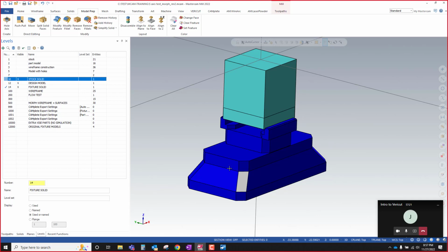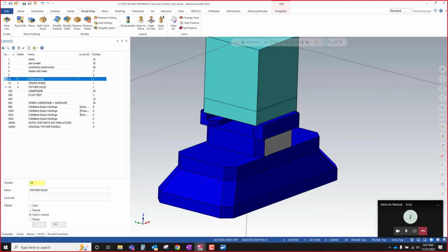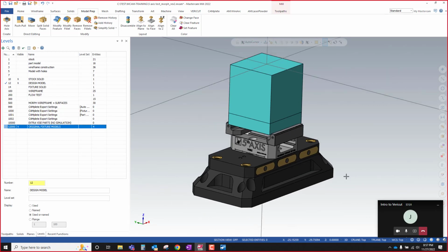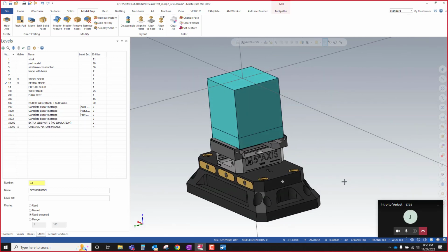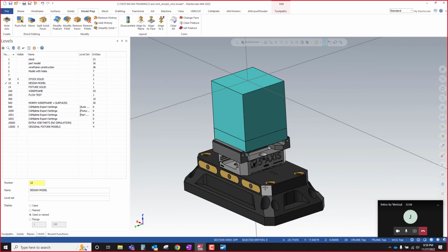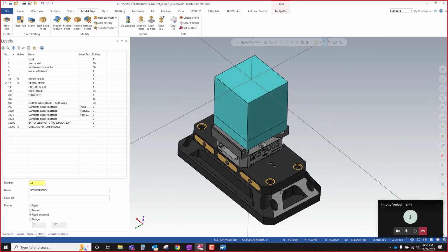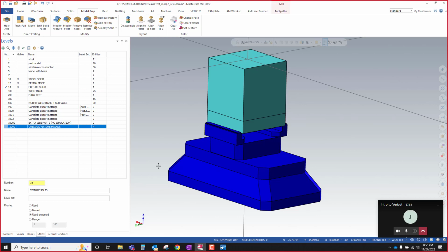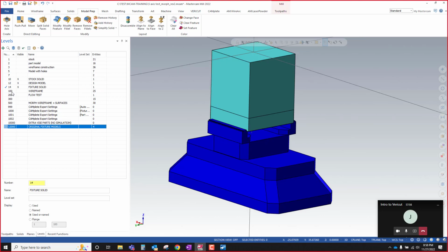You don't have to do this. But if you do it, it's going to make your Vericut run much quicker. So I could have used all that. And some people do. And some people prefer this because they get the visual and they're like, no, I want it to show my actual 5th axis vise and my rock lock base, and I want to see all the holes. And hey, more power to them. I've just done this long enough to know that as long as you have all the exterior surfaces, the simpler you can make it, the quicker the verification is going to be.